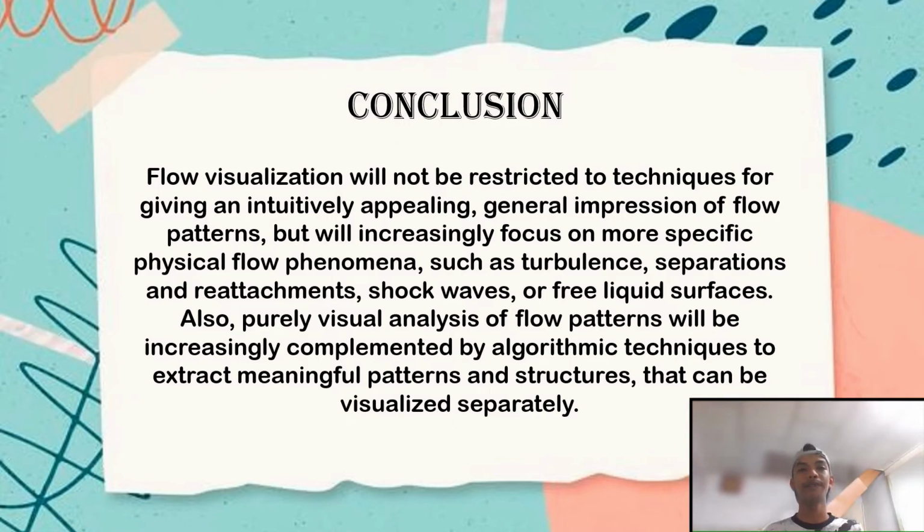In conclusion, flow visualization will not be restricted to techniques for giving an intuitively appealing general impression of flow patterns, but will increasingly focus on more specific physical flow phenomena such as turbulence, circulation, air reattachment, shock waves, or free liquid surface. Also, purely visual analysis of flow patterns will be increasingly complemented by algorithmic techniques to extract meaningful patterns and structures that can be visualized separately.